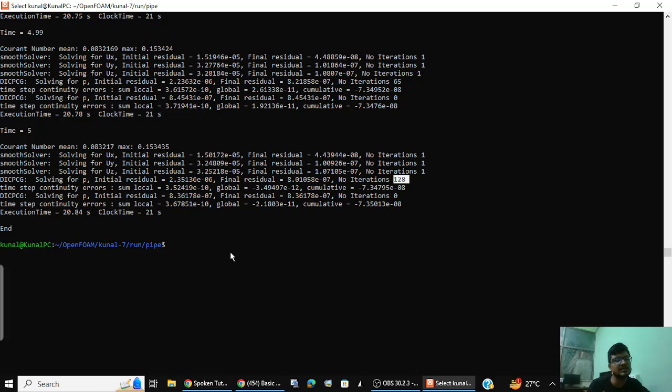The simulations we did till now were just for demonstration purposes, as to how you run a simulation. The standard method includes the calculation of time constants, as to how far the simulation should run such that the steady state can be assumed, for any transient solver. After that, the change with time is significantly small, so you assume that it has reached a steady state. Ideally, perfectly it is not, but it is an engineering assumption. So these are the two things worth conveying.